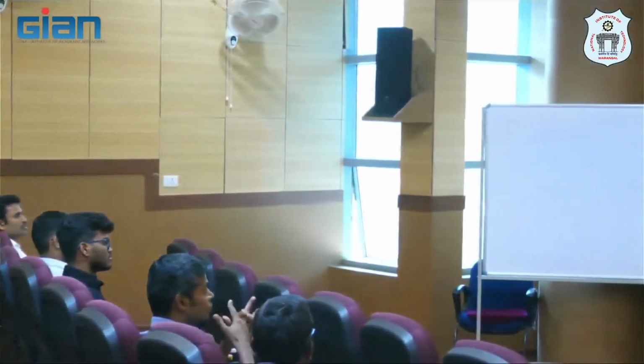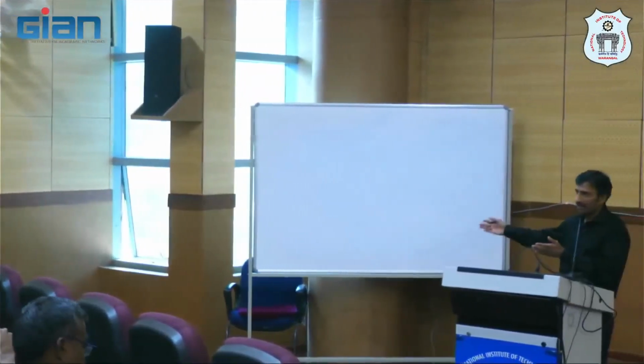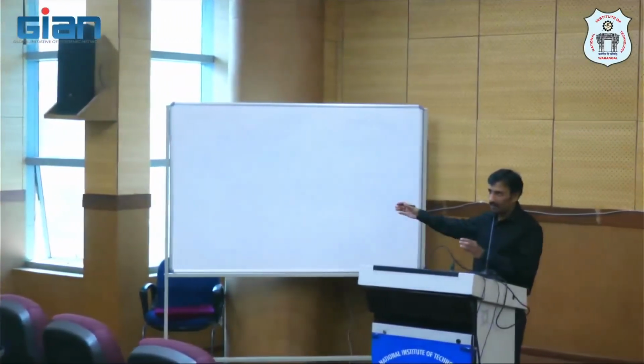Okay, so is the general idea clear? I'm going to start with raw data. We have to do some data processing and generate features. The feature can be multiple quantities. It need not be just one quantity, like RMS, mean, peak or kurtosis. So then the feature becomes a vector. I get a label. I stack feature vectors and labels one below another, and I get my training data set.